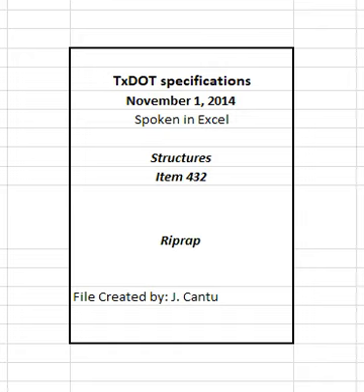Place filter fabric with the length running up and down the slope unless otherwise approved. Ensure fabric has a minimum overlap of 2 feet. Secure fabric with nails or pins. Use nails at least 2 inches long with washers or U-shaped pins with legs at least 9 inches long. Space nails or pins at a maximum of 10 feet in each direction and 5 feet along the seams. Alternative anchorage and spacing may be used when approved.